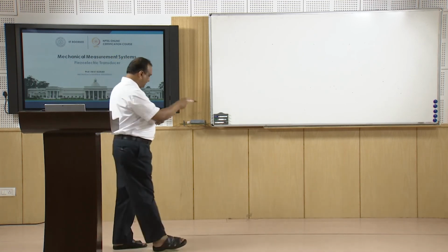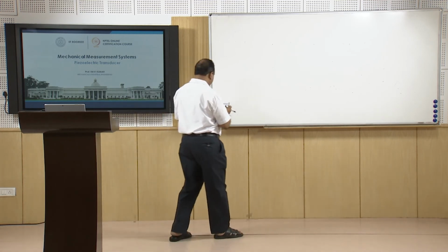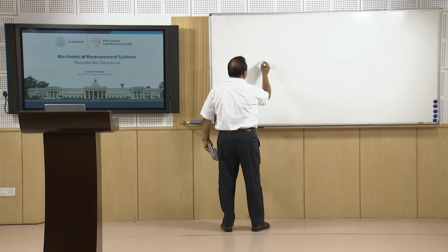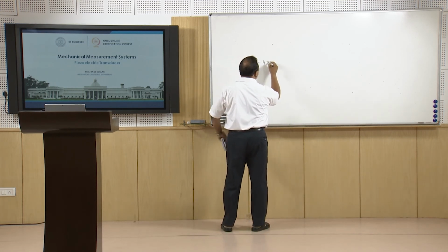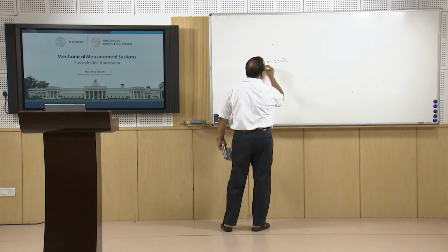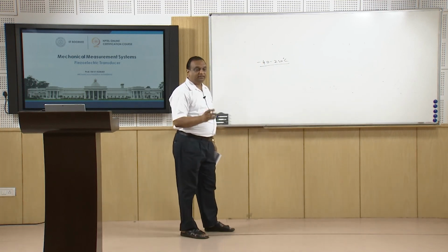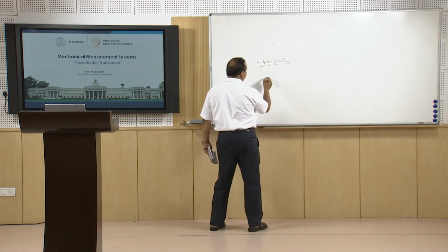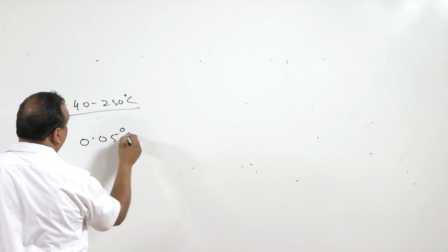Now the quartz crystal works over minus 40 to 250 degree centigrade temperature. The deviation from the linearity is 0.05 degree centigrade.